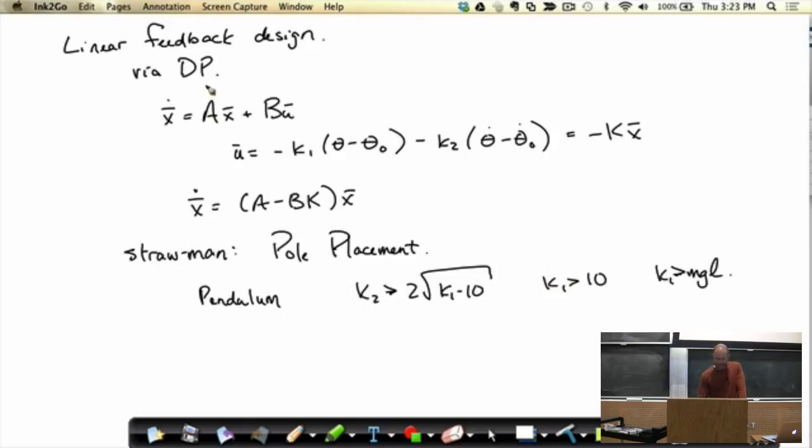What we're going to get today instead is by formulating an optimization problem, saying I'd like the response to be optimal by some metric. You might complain that you have to choose the cost function, I have to choose my weights. But for any choice of weights, as long as you say positive weights, for instance, you're going to get a stable controller out. It's just a much nicer design space to work in. For any objective function I give, I'll get a stabilizing controller, and I've changed the game from finding a stable controller to shaping the controller to the one I want.